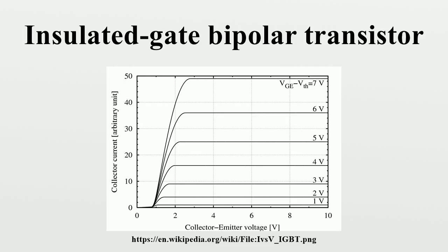The applications for the device were initially regarded by the power electronics community to be severely restricted by its slow switching speed and latch-up of the parasitic thyristor structure inherent within the device. However, it was demonstrated by Baliga and also by A. M. Goodman et al. in 1983 that the switching speed could be adjusted over a broad range by using electron